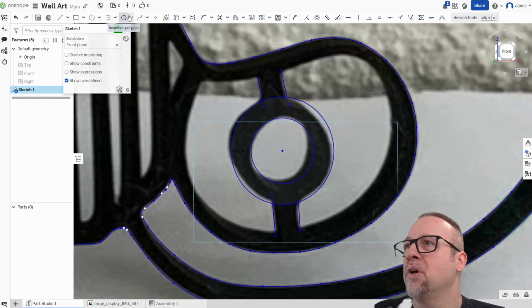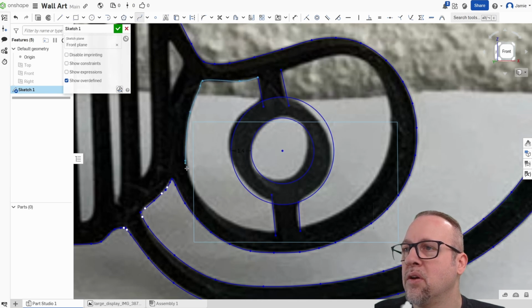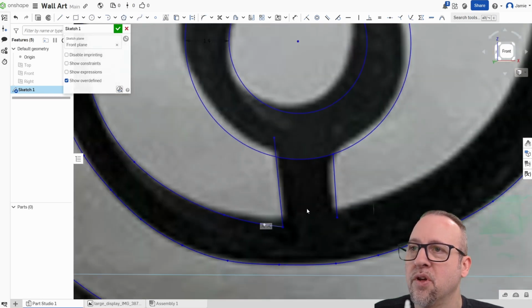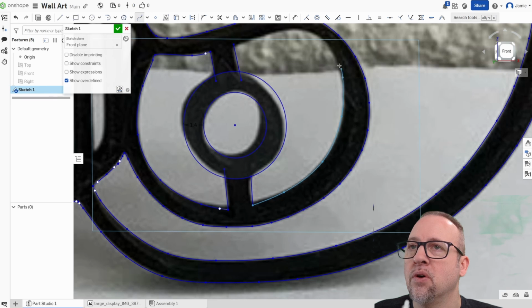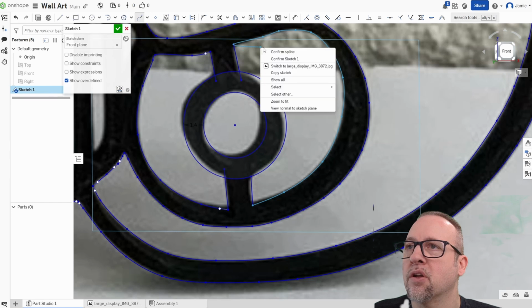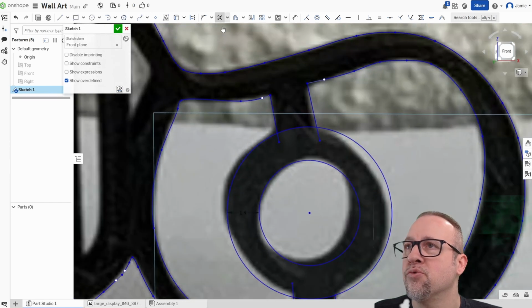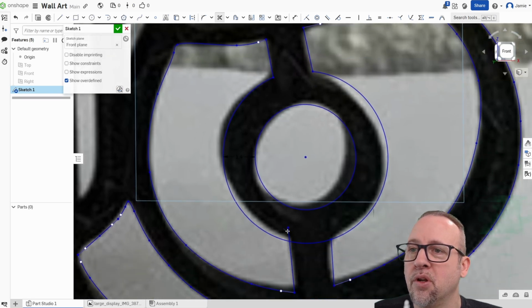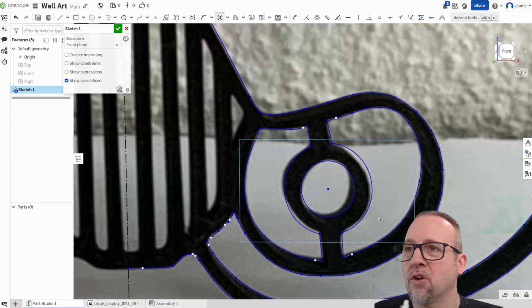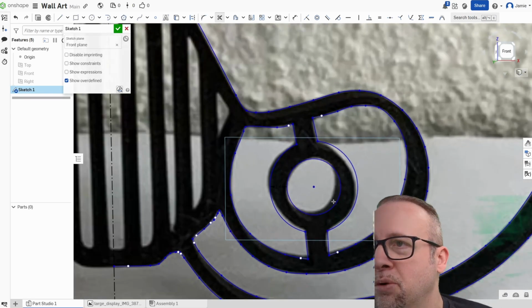So now I'm going to get my spline here to here. Okay, yep, looking good. Right click, see how I definitely make sure that's connected, and now I'll do the center one, spline. And I can adjust that after if I really want to. Connected, right click, confirm. Okay, now we're going to do some trims. Trim that guy, trim this guy, so it breaks my circle. Okay, but look how pretty it looks. Broken, fixed, everything. Don't worry about this square, that's probably a sketch.